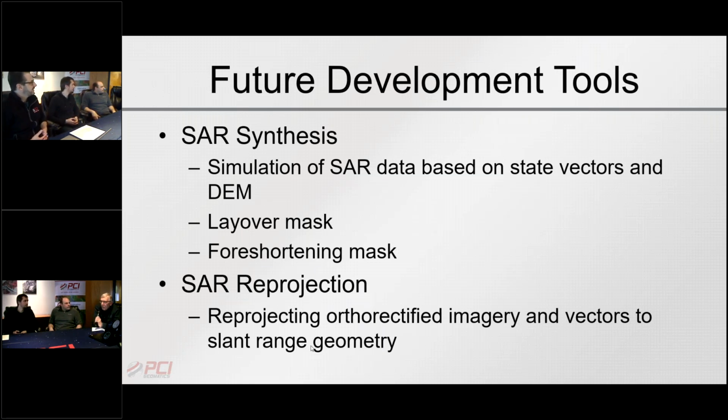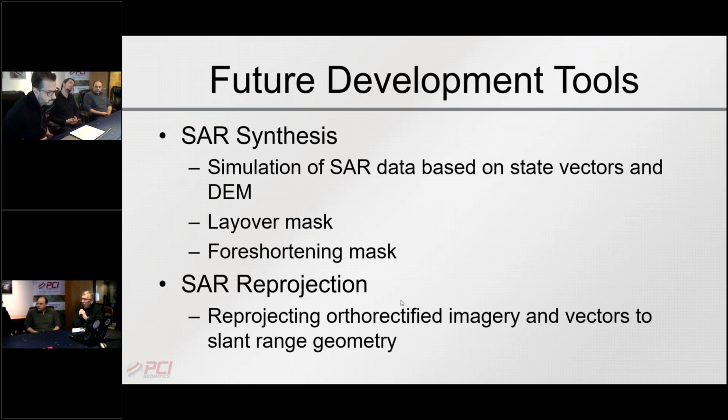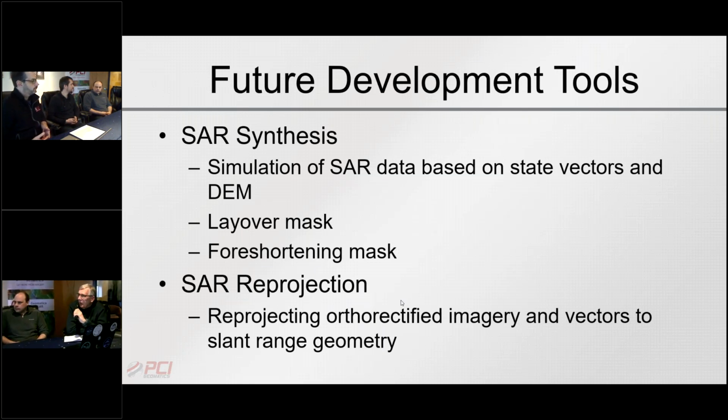Well, there's a couple of things to consider. Clearly if it's slowly deforming, then you don't need to get data very often. The critical thing is you have to acquire data at least at a rate such that whatever is moving hasn't moved more than half a wavelength. So obviously if something is moving quicker, then you probably want to go to a longer wavelength. If something is moving relatively slowly, then shorter wavelengths are probably the way to go.